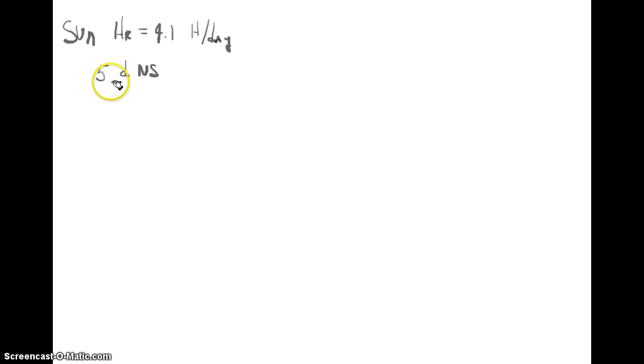All right? So how much energy does it require? How much energy do we have to store in that battery for 5 days? Well, we already know that we're consuming 1,200 watt hours a day, and if we want 5 days, that turns out to be 6,000 watt hours our battery has got to hold. All right, now let's talk about batteries.